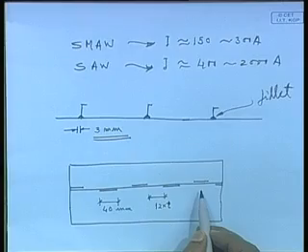Say the side shell, main hull girder, whatever stiffener is being welded, or the deck plating, the deck longitudinals, bottom shell plating, the bottom shell longitudinals, side shell frames, all longitudinal, that means primary stiffening members, you cannot do stagger welding, because obviously this kind of welding will lead to less distortion, but at the same time less strength, which cannot be afforded.